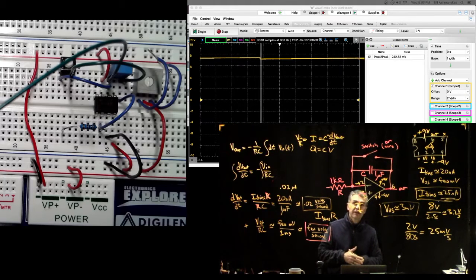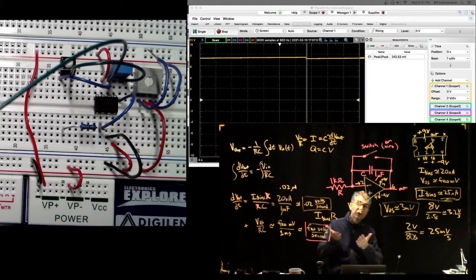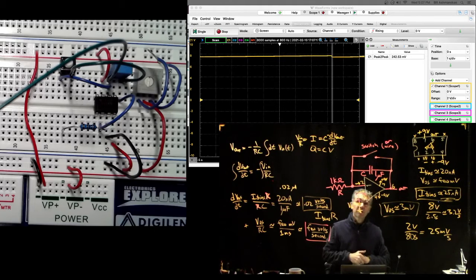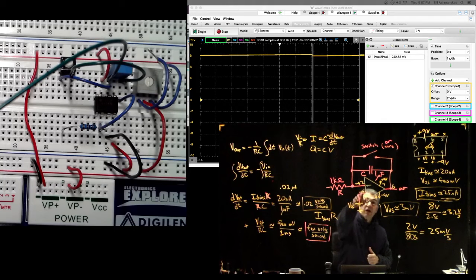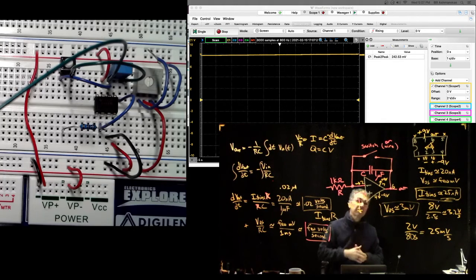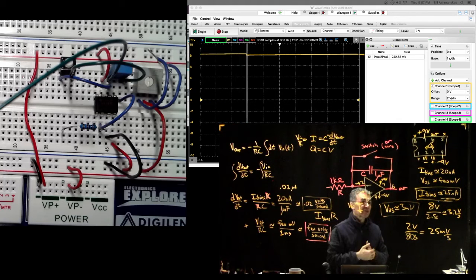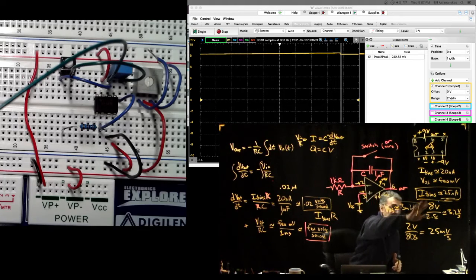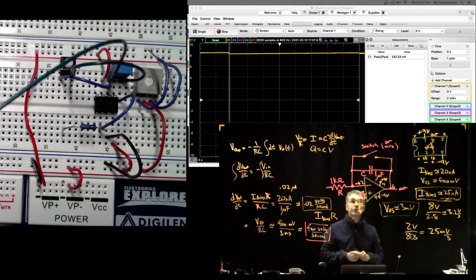I worked it out. And then it also shows you that an op-amp integrator is an example of a circuit where you have to be pretty careful about controlling these things. And the way you control it: you can buy better op-amps that have a relatively small V offset, but even then you usually trim V offset carefully with this little trim pot that I'm going to show you how to use in just a minute. And if you buy an op-amp that has field effect transistor inputs instead of bipolar junction transistor inputs, it usually has a much smaller I bias, so then the I bias effect becomes negligible. So you buy a better op-amp that gets rid of the I bias effect, and then you can adjust to trim out V offset. That gets rid of that problem.